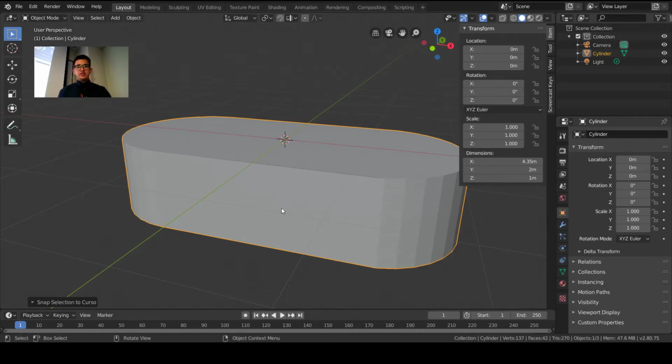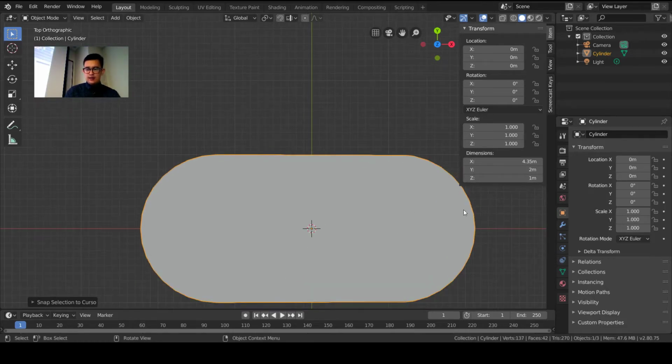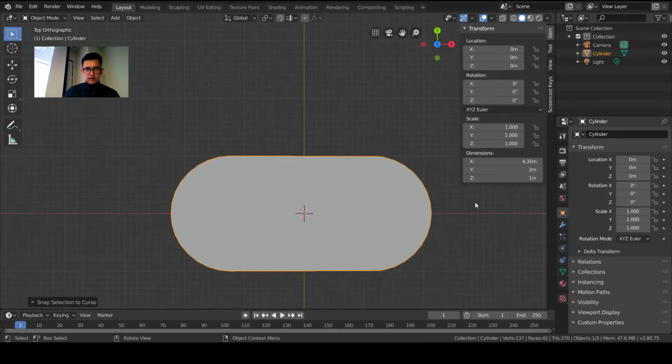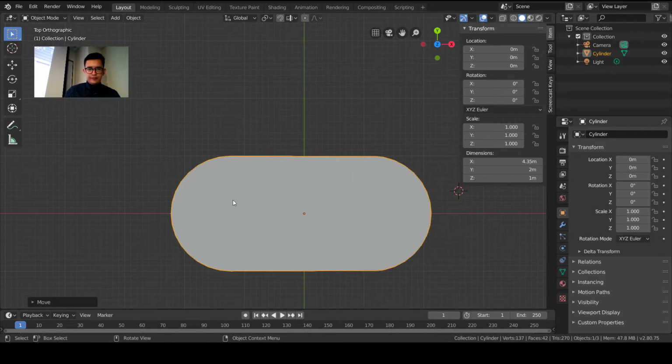So for this, I'll teach you how to use the extrude tool, and if you use SolidWorks, it's kind of similar where you can have a 2D shape or a sketch and extrude out of that to make a 3D shape. Okay, so let me go back to my top view like that. Let me go over some of the hotkeys again for movement, just in case you're trying to follow along and you're getting stuck.